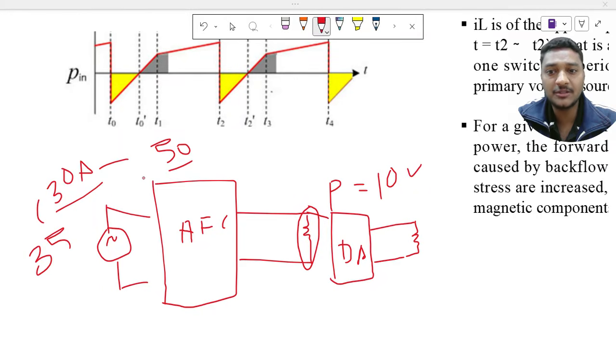I have done this simulation myself, and I also observed that the current is really high, some sort of change from 30 ampere to 50 ampere. One more important thing I forgot to mention: even though my power factor is unity, and my input current and input voltage are both almost sinusoidal with THD less than 5%, I still observed this phenomenon.